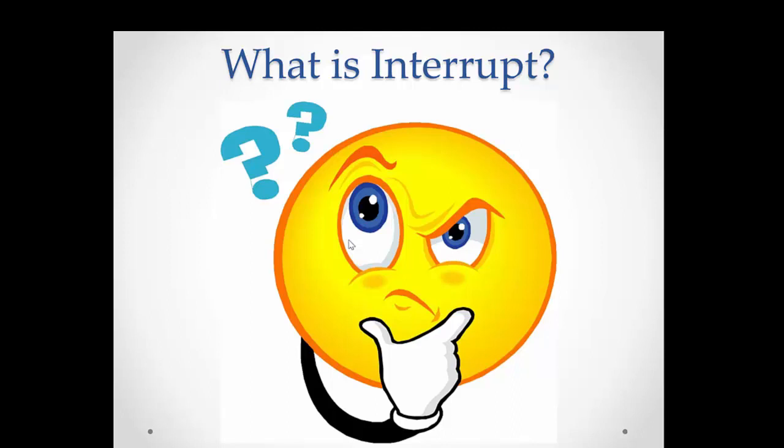And how do we do that? Using interrupt. Now there are different types of interrupt. There is something called software interrupts, and there is another thing which is called hardware interrupts. Software interrupts, such as the ones associated with overflow registers. So far we know that the PIC16F887 has an 8-bit size register.